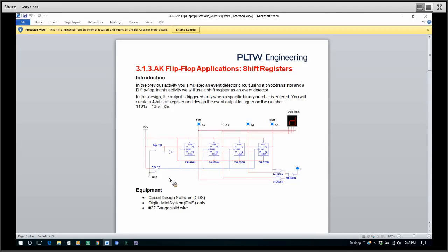The other thing is, you notice they've got switches out here, and you can't have switches in a PLD. So the kids can build this. What's nice about it is up here they've got an output. Instead of looking at the binary numbers, they can look at this. And this is not a normal 7-segment display. A 7-segment display has 7 wires to it for each of the segments, A through G. This one only has 4.